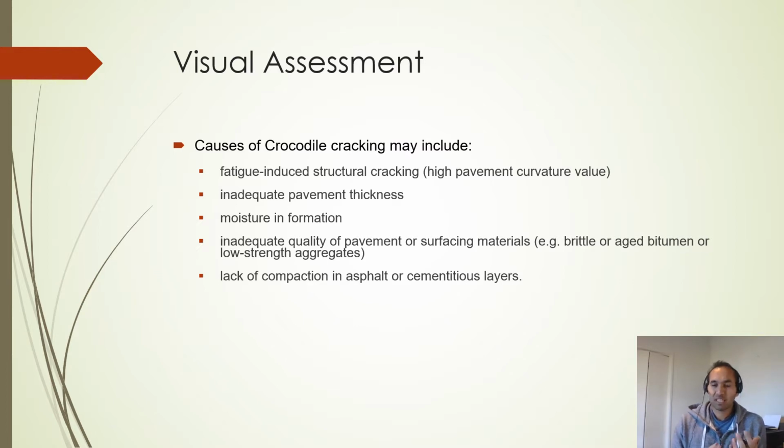Sometimes it's just excessive loads. You could just have heavier traffic that the initial pavement wasn't designed for. That could lead to significant rutting of the subgrade, but it could also lead to asphalt fatigue. You get a lot of stresses induced in the asphalt, causing tensile strains at the bottom, which leads to fatigue of the asphalt. If you do deflectometer testing, this is often represented with very high curvature values. As we continue with this presentation, we'll see where that happens and where that doesn't happen.